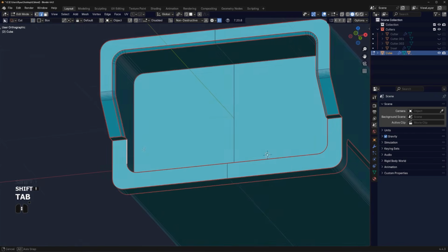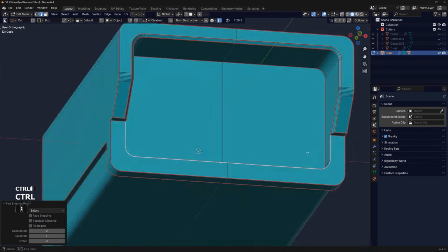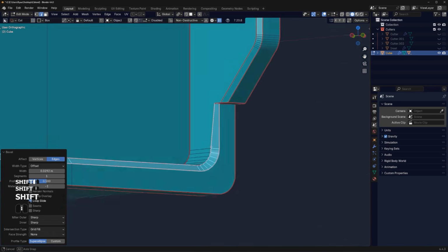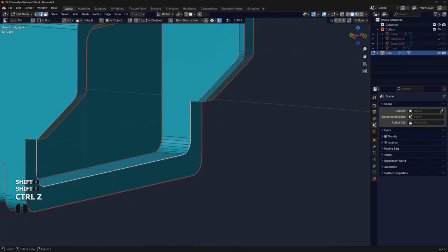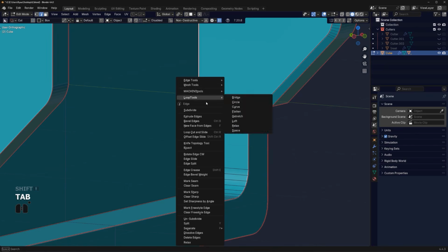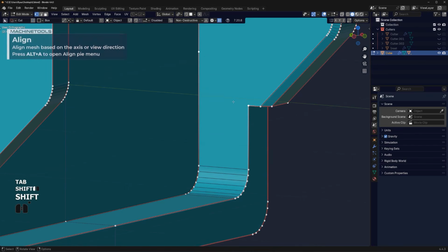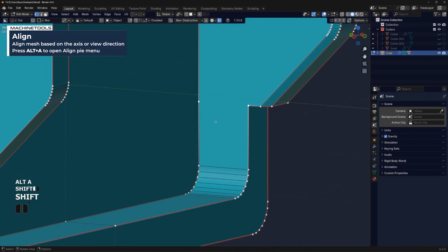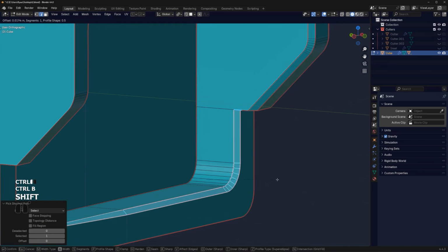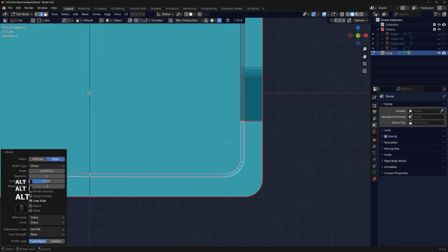Well, it would be awesome if I could also run a chamfer here, which is gonna be a bit problematic. You see, when you have this kind of situation, you want to extend these edges. So you subdivide this edge here, you bring this vert down with machine tools, you create an edge here to guide the bevel, and then, you know, Bob's your uncle. See what I mean? I mean bevel, chamfer, that's what I meant.